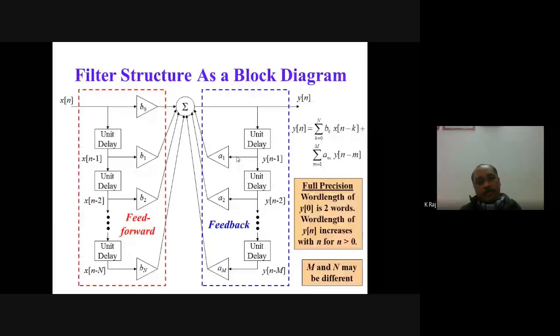As we have discussed, using the DFG, that is the data flow graph, we can demonstrate one iteration of any algorithm. With the help of the DFG, we can reduce the computational cost by using the pipelining and parallel concept, and we can also introduce retiming, folding and unfolding types of algorithms in order to reduce the number of additions, multiplications, and memory devices here.